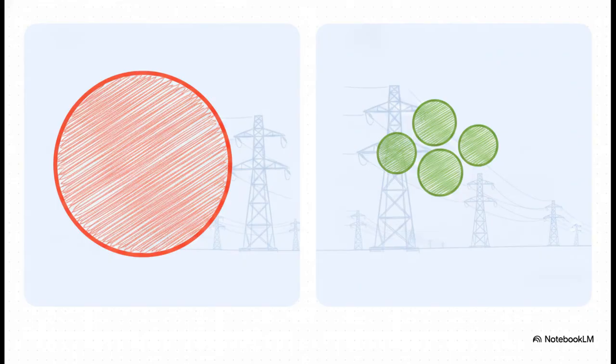And this leads to a massive economic payoff. Because three-phase power is perfectly constant, with the pulsations from each individual phase completely canceling each other out, you can deliver the exact same amount of power using significantly less copper than an equivalent single-phase system. You literally just need smaller conductors. That is the huge structural advantage that made three-phase the default for every transmission line on the planet, drastically reducing material costs across thousands and thousands of miles.